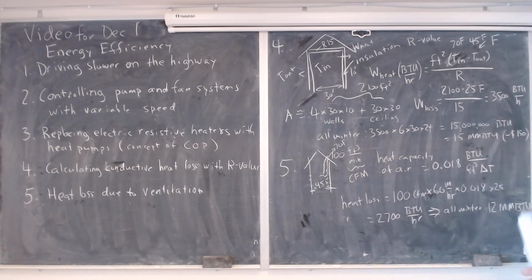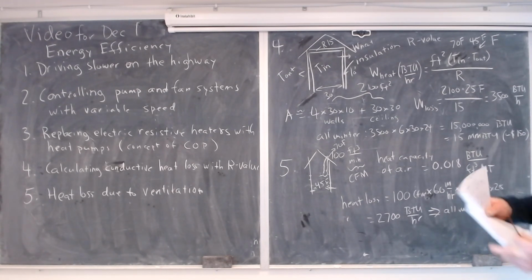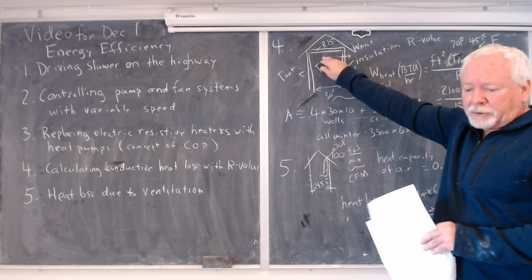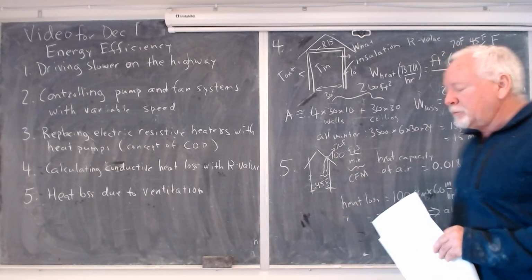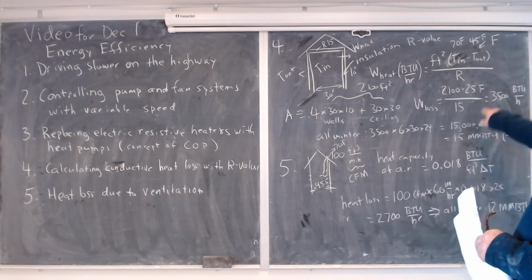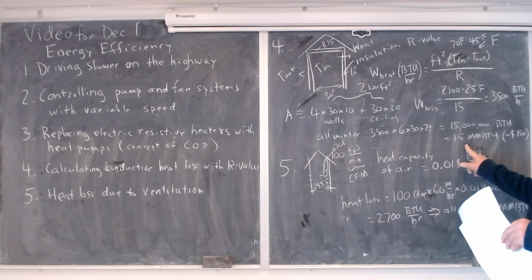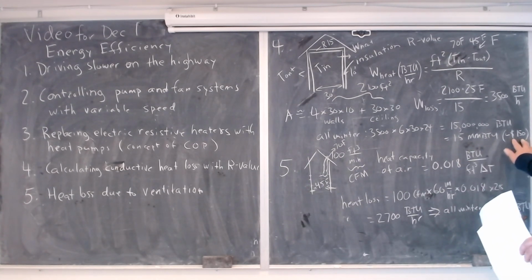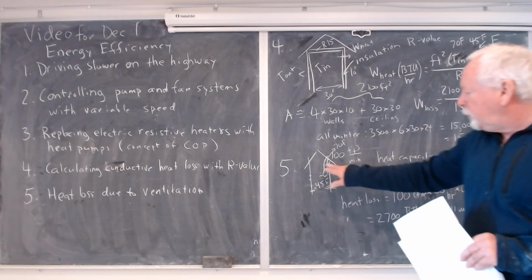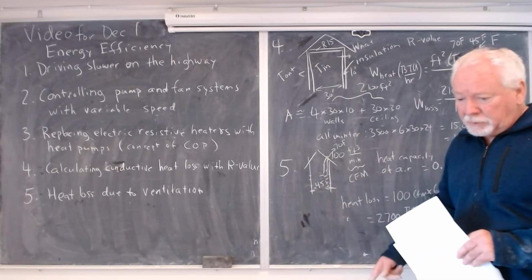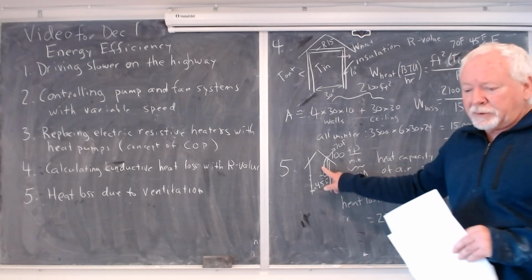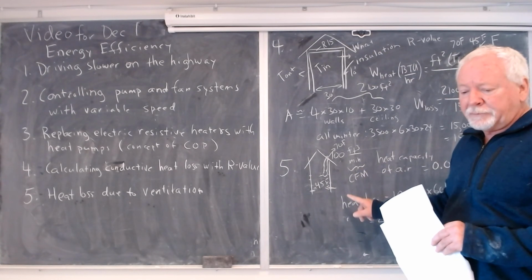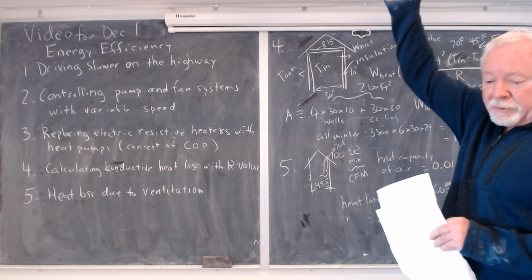All right. So I've illustrated two ways you lose heat from your house, for example. One is through conductive loss through the insulation. And if you're insulated well with R15, which is reasonably high insulation value, you lose 5 MMBTU every winter. And so that costs you around $150 in heating costs. If you have a bathroom exhaust fan that's running continuously, you lose almost as much, 12. With one little exhaust fan, that's a tiny exhaust fan, 100 CFM. And that's like one of these little bathroom exhaust fans up there.